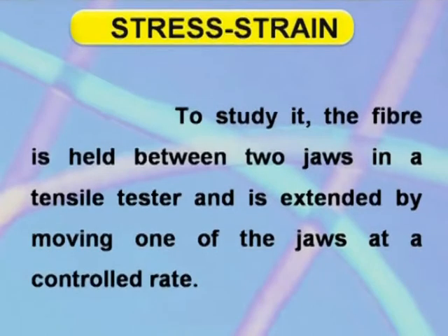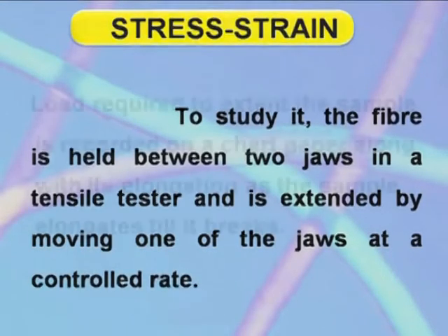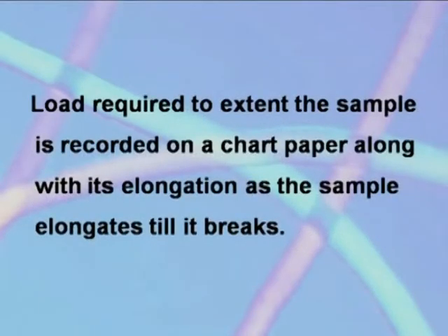To study it, the fiber is held between two jaws in a tensile tester and is extended by moving one of the jaws at a controlled rate, and the load required to extend the sample is recorded on chart paper along with its elongation as the sample elongates till it breaks.